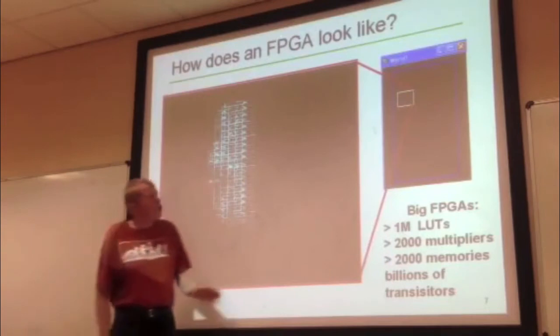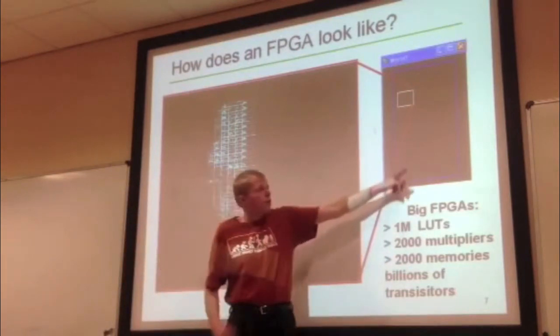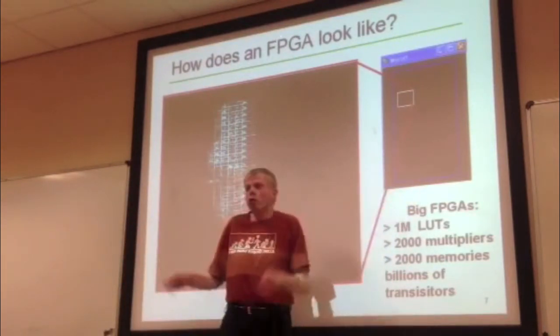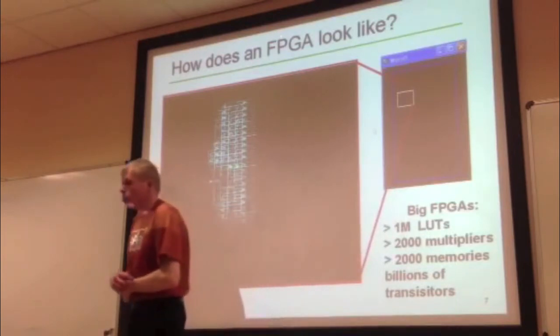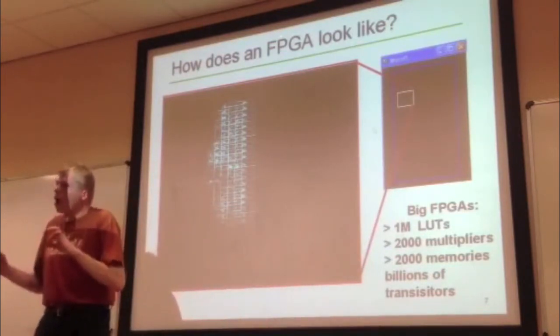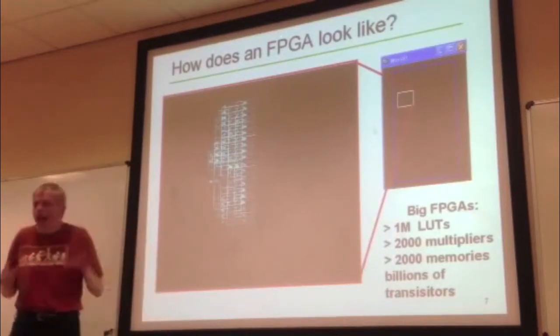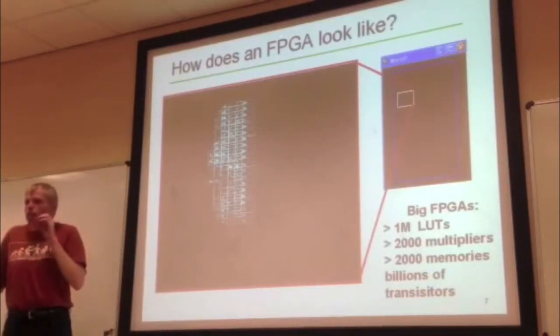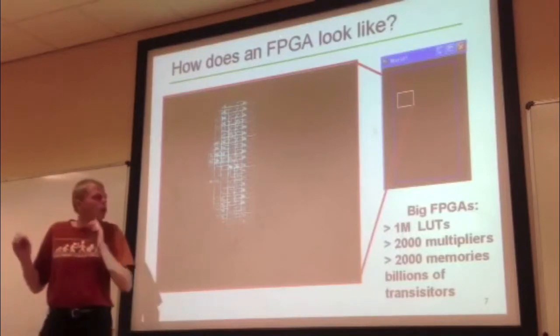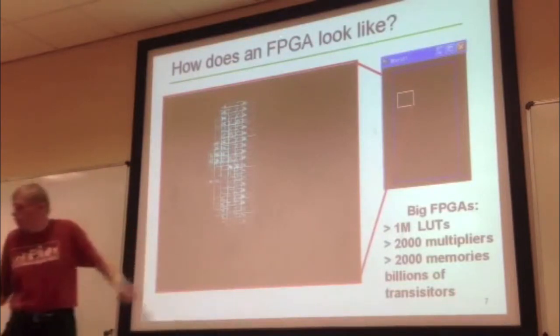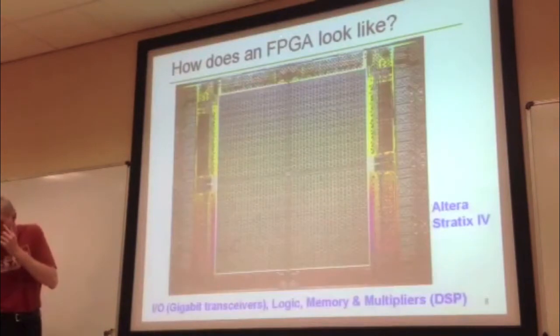The FPGA shown here, which is one I have in my office, could probably host something like 50 32-bit processors. But that's typically not the way you use an FPGA. It can implement a processor, but you can implement algorithms much better than by using a processor you load on them. I will come to that a bit later.